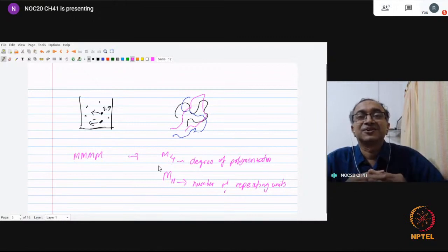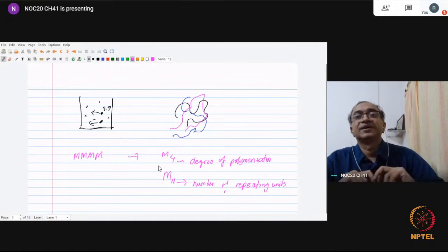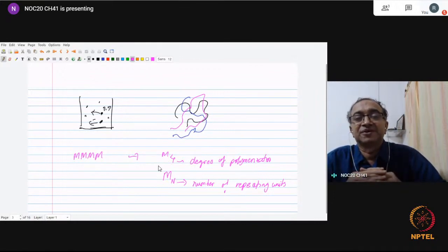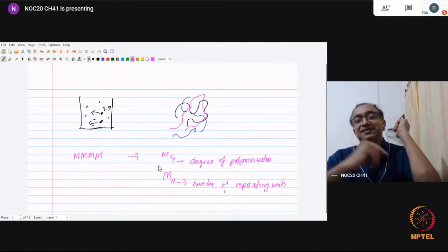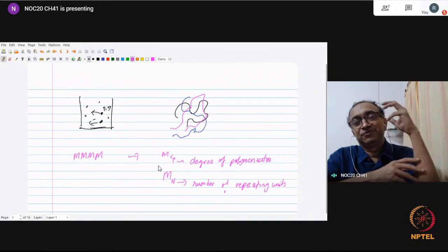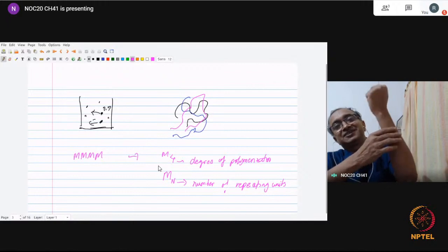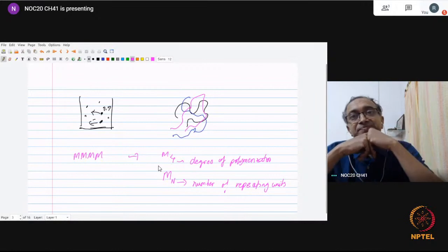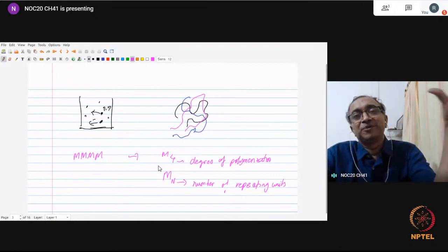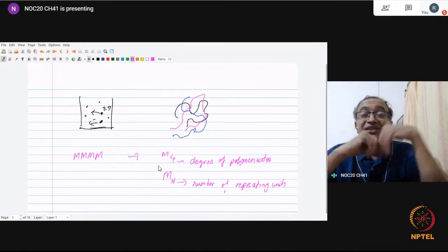In the end, glass transition is related to what's called a segment of a polymer chain. We generally talk about a macromolecule being very long. I don't know if you can visualize, if a polymer's diameter is like my hand, about 4 or 5 centimeters, what is its length? Its length is going to be in kilometers. So it's an extremely long object. But the bond angle, rotation, and all of that is happening at a very small scale.